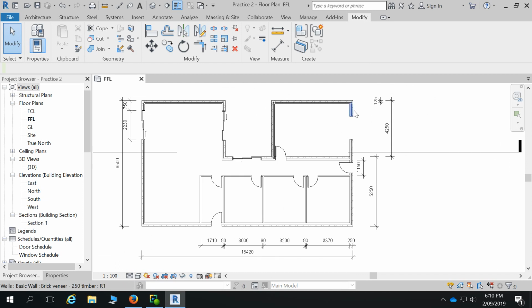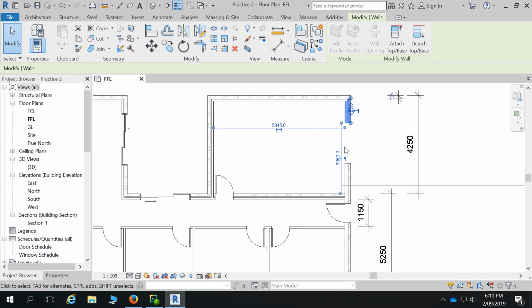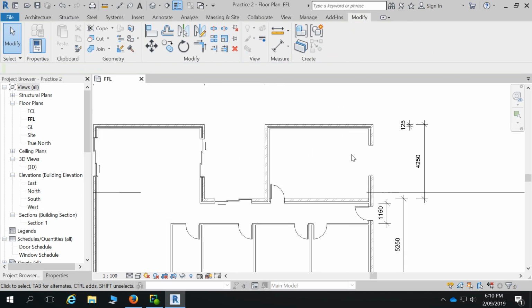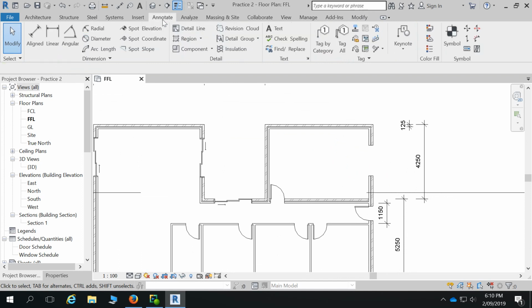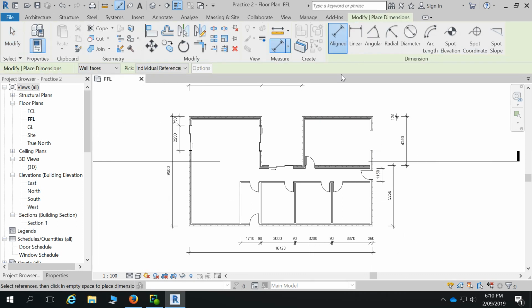the easier way to then get that distance open is, rather than try to use these temporary dimensions that aren't going to be in the right spot, where you've got to start to move the nodes around, to set up some permanent dimensions there. When you set up a permanent dimension, it's really in the Annotate tab, and you get all this dimension panel here. But one of your shortcuts, and I'll introduce certain ones every week, is DI. It will get you straight to an aligned dimension. So DI gets you straight into this aligned dimension tool, ready to do a dimension.